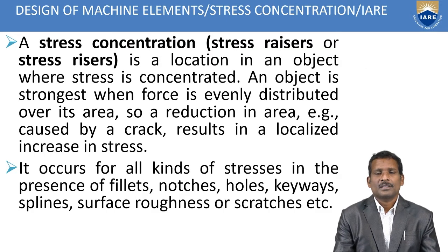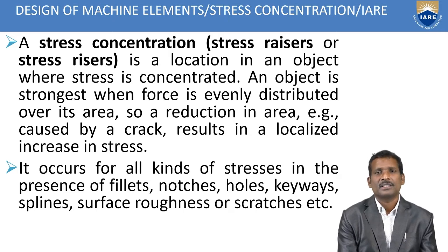Stress concentration means a location in an object where stress is concentrated. Already we have discussed, an object is strongest when force is evenly distributed over its area. So a reduction in area, for example caused by a crack, results in a localized increase in stress. Due to this, suddenly it may change its area.